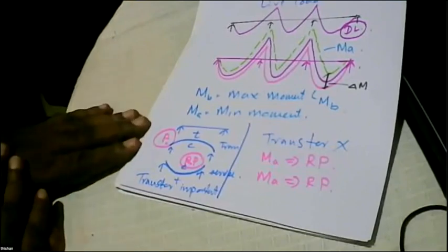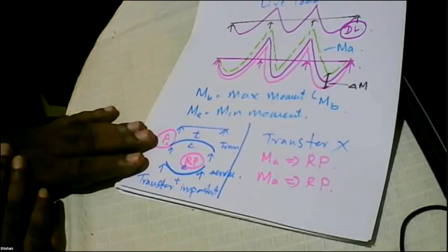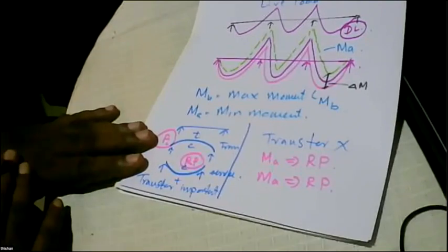So that is the clear difference between the precast simply supported construction that we often use, where we can't afford to have a shuttering system at the site because we are constructing these waterways and motorways and all these roads. So we cannot afford to have a proper shuttering system. So what we do is we go for precast construction and also have in situ cast wider top flanges. So you will find that they cannot fail easily. Why?